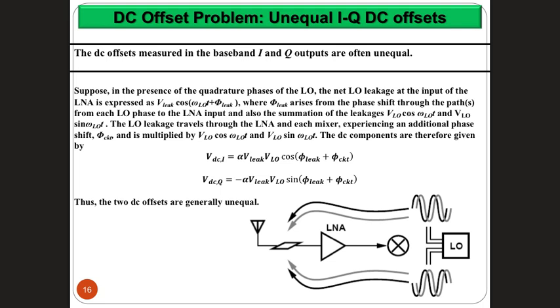Yes. OK? And then the cosine and the sine feeds on the cosine branch, and the cosine and the sine feeds in the sine branch. OK? And then they're added up again. And then if there are some phase shifts between them, OK? If they go through different circuits, which is most of the time, for example, the branch that goes for the I and the branch that goes for the Q has some imperfections in their manufacturing, so there is a slight change in terms of the wire lengths or whatever.